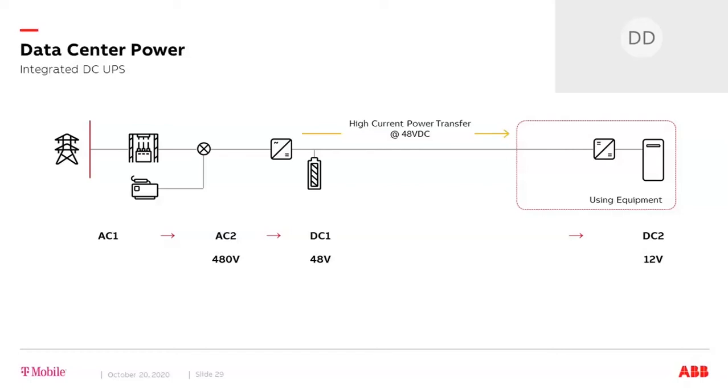This revealed to us that eventually we'd need to move the batteries and conversion modules even closer to the loads, into each IT cabinet. We needed much more power per cabinet, so higher voltage was needed. By selecting 480 volts AC power distribution, we maximized the power available from our low voltage utility source. Fortunately, ABB embraced this idea and developed the Edge system architecture to enable it.